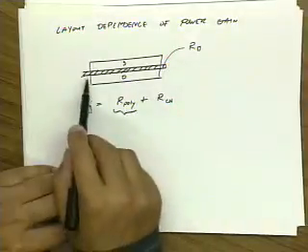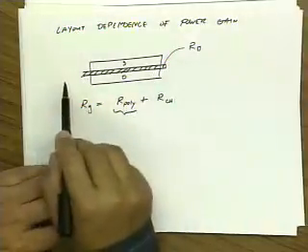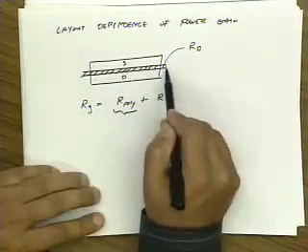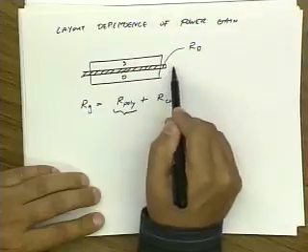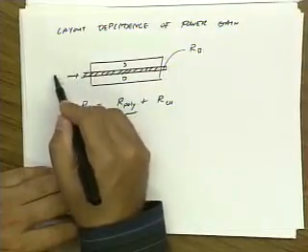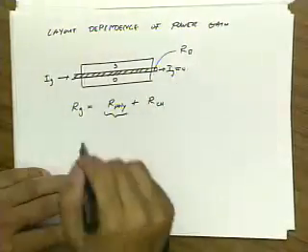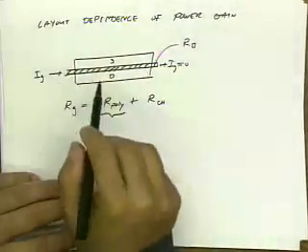Now it turns out that this is actually a distributed structure, because the current that goes into the gate doesn't all flow to here, right? The boundary condition is actually the current. So if I have I gate coming in, here I gate is 0 because I have current going down vertically into my device.